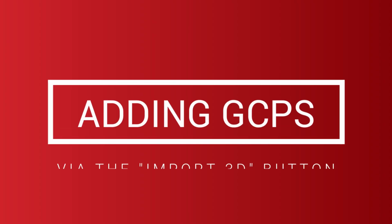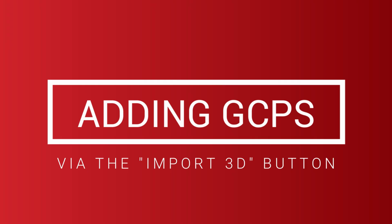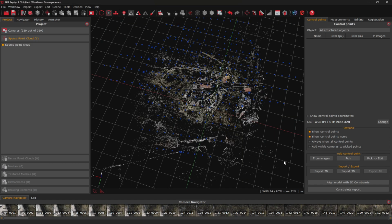Now, let's see how to work with ground control points. There are 2 ways to add ground control points in Zephyr. The first method is clicking Import 3D in the Control Points panel. To do this, the current project and the coordinates you're importing must use the same coordinate system.